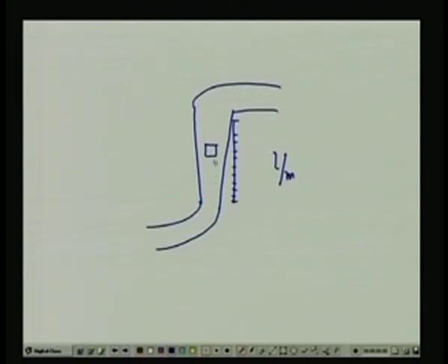By looking at the position of the bob, I can tell what the flow velocity is. This is very important in the case of the rotameter. It is basically used as a monitoring or indicating instrument, but not as a transmission instrument. That does not necessarily mean its accuracy is poor. Accuracy is quite good in the case of the rotameter, and it is extensively used in anesthesia.